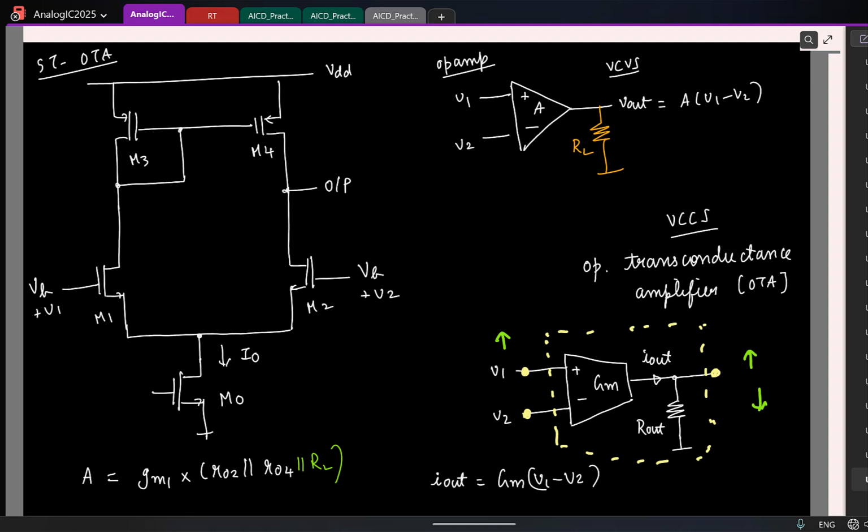Same thing we'll do here. So let us say I increase this voltage here. What do you think will happen to this drain potential? Common source. I mean, this is all small signal calculations. Remember, I'm increasing the small signal gate voltage. This is the cause. So what will be the effect of this? Drain current will increase.